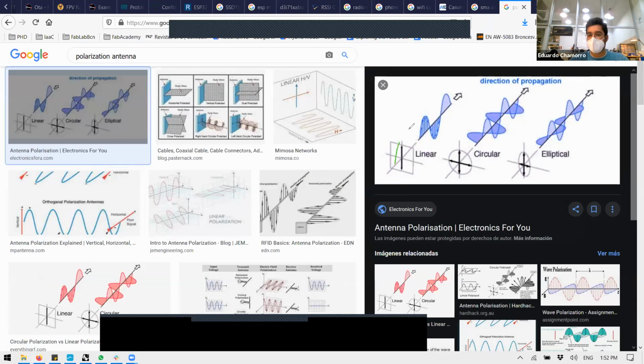So in a linear antenna, the signal more or less stays flat and stable in space. A polarized antenna, what it does is the wave rotates three-dimensionally, for example, to the right or to the left. And you can produce the same signal rotating to the right. You do this with the antenna design. So actually you are able to transmit on the same frequency, but the signals cannot be coupled to each other, synced, because they basically rotate in opposite directions in space three-dimensionally.